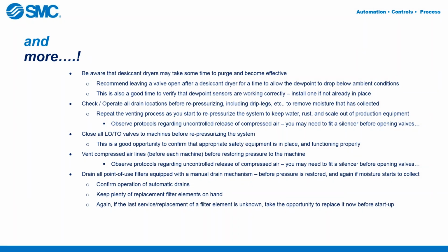Some other points: desiccant dryers may take some time to purge and become effective, so you may wish to leave a valve open after a desiccant dryer and let the dew point establish to some acceptable level below ambient conditions, so that you're not inadvertently sending moisture downstream into your system.